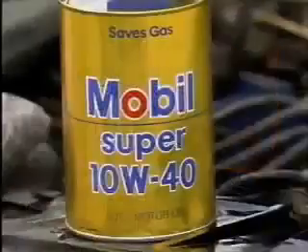So, the type of oil selected for a particular application depends on the temperature it's used in. In low-temperature applications, lower viscosity oils are usually more suitable. They flow more easily at low temperatures and can reach moving parts better than thicker, high-viscosity oils. In high temperatures, a thicker, high-viscosity oil is usually needed. The oil has to be thick enough, that is, have a high enough viscosity to maintain a film over the moving parts it must protect.